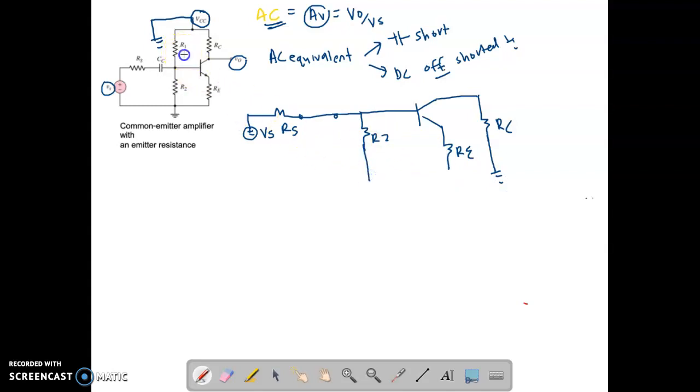But now where does R1 go? So here you have R2. Now look at R1. See point A. R1 is connected to point A and to ground. So you can make your R1 and R2 parallel, and the whole here will be grounded. Now let's locate where your output is. Your output is at your collector and your input is at your base.